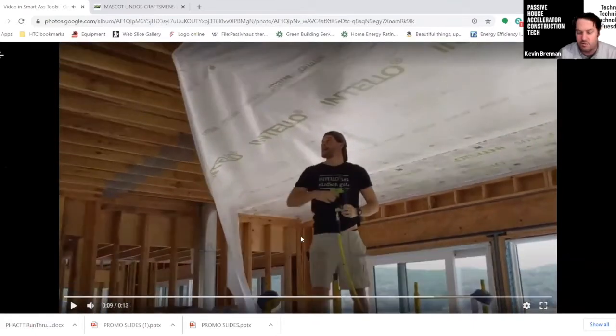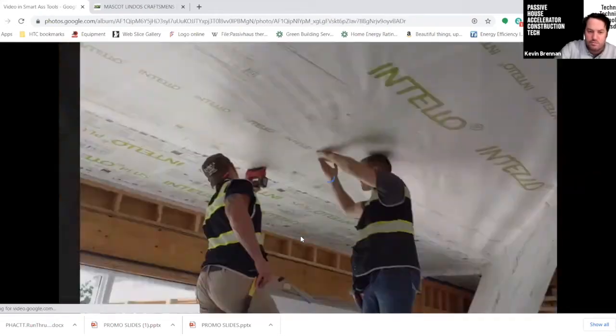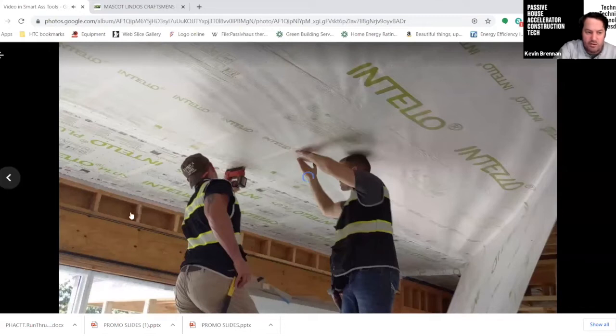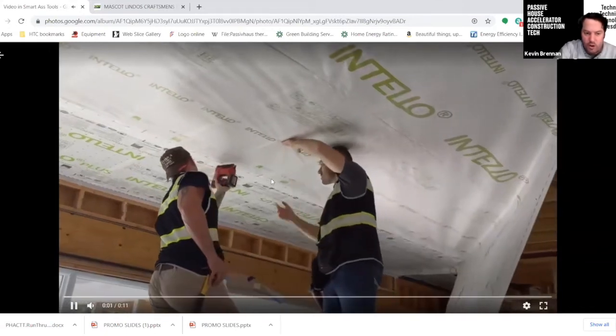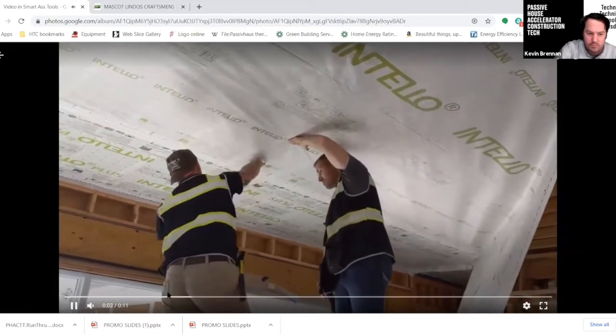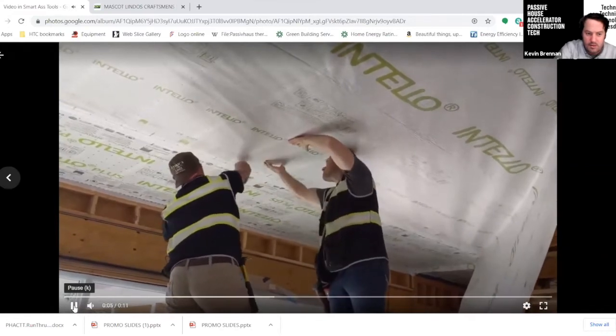So the manufacturer recommends that you staple every 4 inches. In order to make sure that that happens, we go pneumatic, and that thing is almost semi-automatic in that it doesn't really need that space in between. That's called the G-Rex, and it takes T50 staples, which is really nice. And this next video shows us going with the Milwaukee.